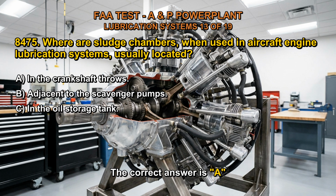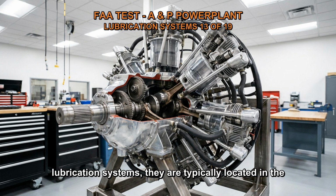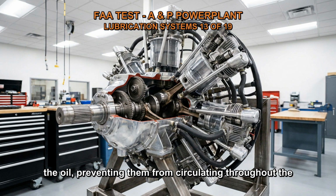The correct answer is A. When sludge chambers are utilized in aircraft engine lubrication systems, they are typically located in the crankshaft throws. These chambers serve as reservoirs for collecting and separating any sludge or solid particles present in the oil, preventing them from circulating throughout the engine and potentially causing damage to components.